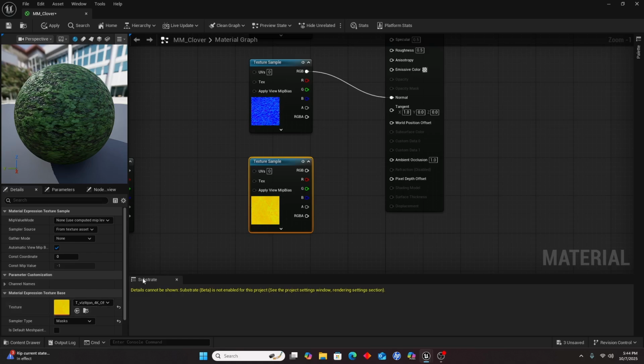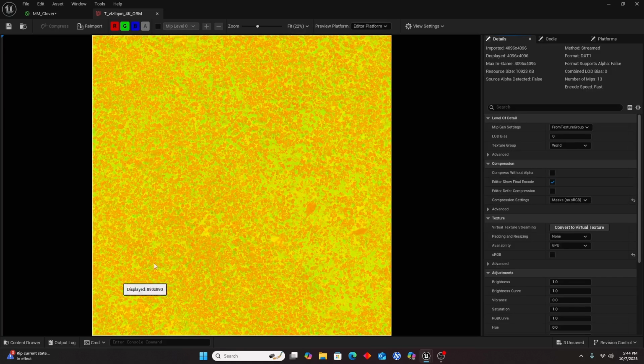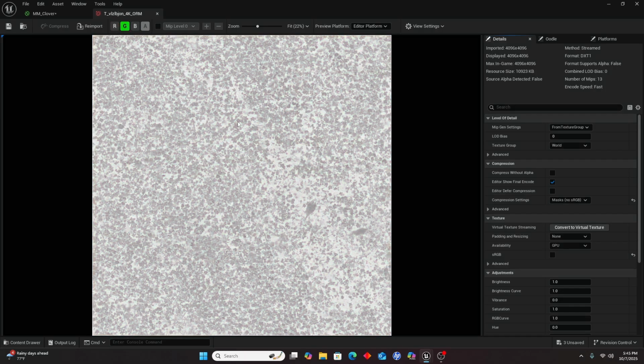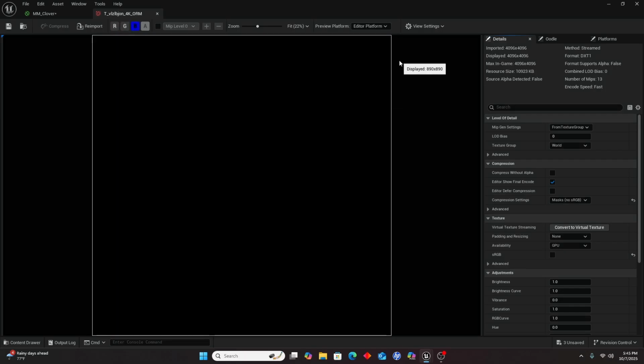A packed texture is essentially three black and white textures packed into one. If I turn this off, this right here is my red channel, then this is my green channel, and if you check this out, this is my blue channel.